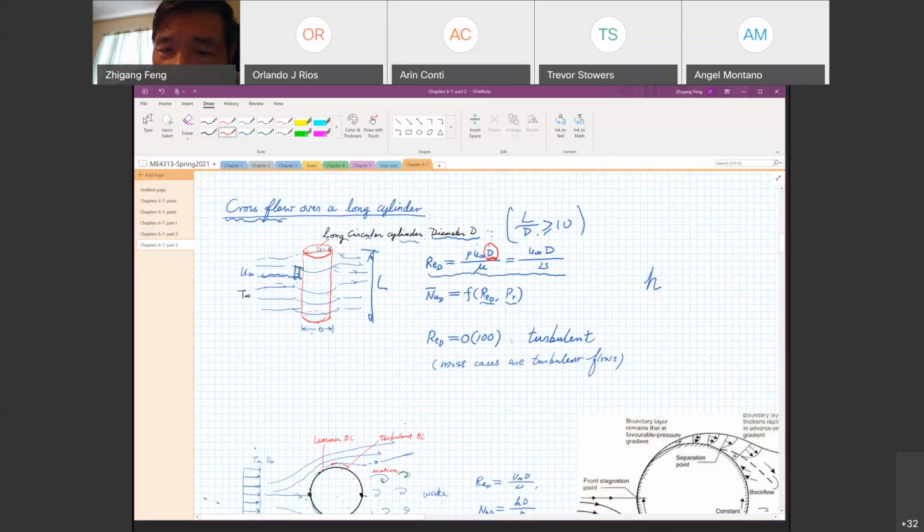So for this lecture, we gave you the formula. The only thing you need to pay attention to is these small details. How do you choose the thermal property? That's one. How do you choose the reference value? For example, how do you choose the reference length? For a long cylinder, it has to be the diameter. I'm sure for some it's kind of boring because I repeat so many times. But still, I'm pretty sure some of you will make mistakes.